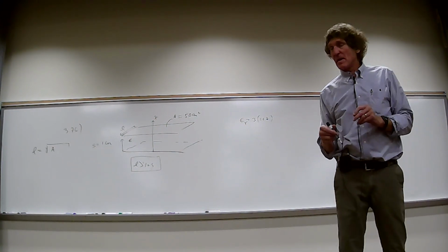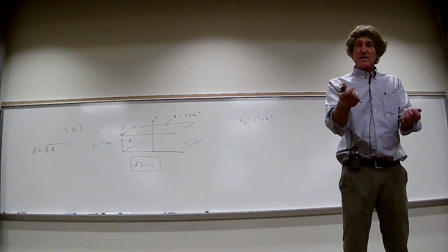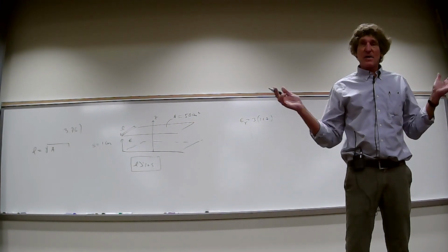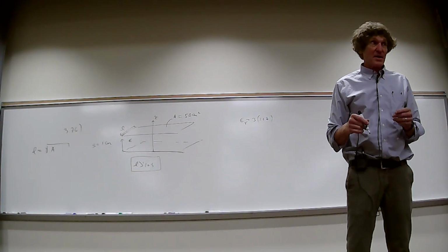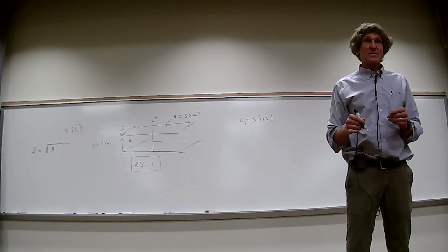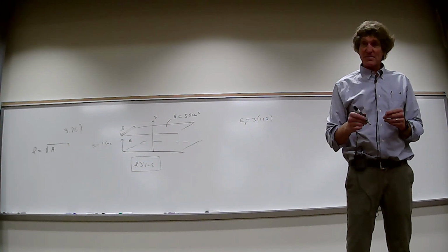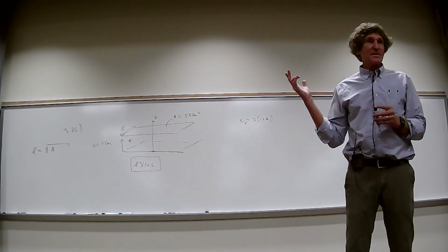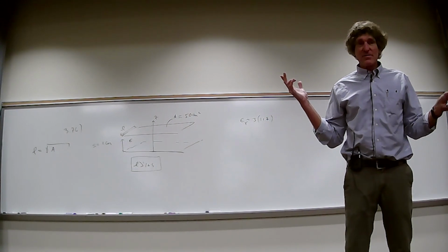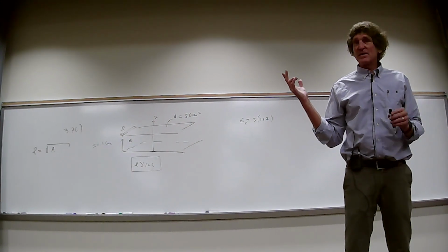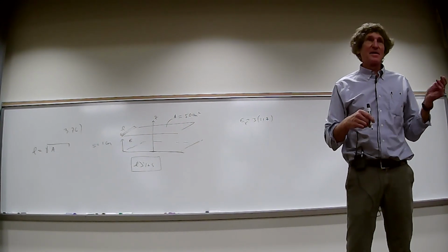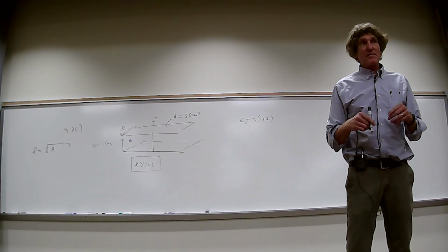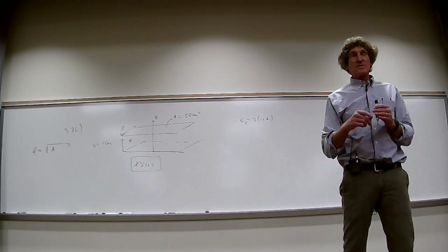Usually say maybe 100 volts. Take that 100 volts to C, and then you discharge. The kids are shocked. I made a capacitor. That is a capacitor. But if you keep upping the voltage, all of a sudden, you're going to bust through the wax paper. That's called breakdown. Has anybody ever blown up a capacitor? You have? In the labs, I've seen kids do this on purpose. It's loud.